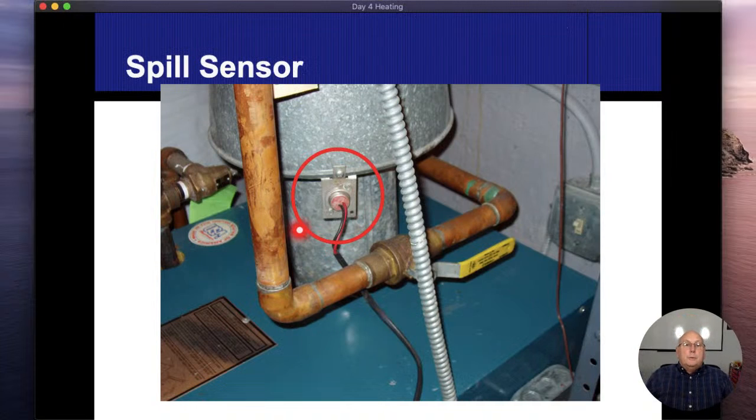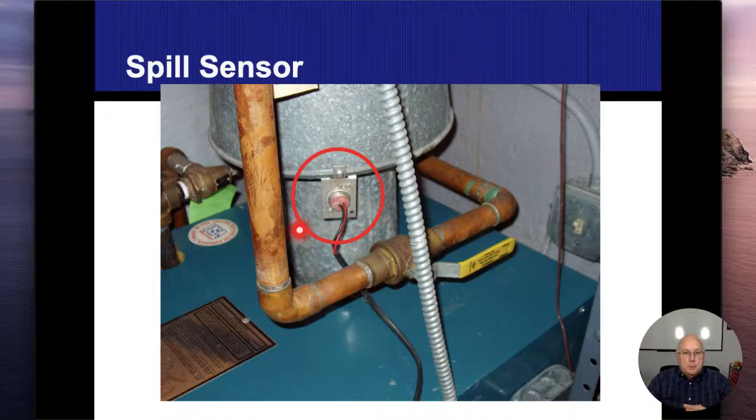So what we started doing for safety features is they started putting backdraft sensors on these things. And they're nothing more than heat sensors, all right? This is an aftermarket one on a hydronic boiler that's on there. So that if the heat is coming down and in, this is going to sense that heat and it's going to shut our boiler off, all right?